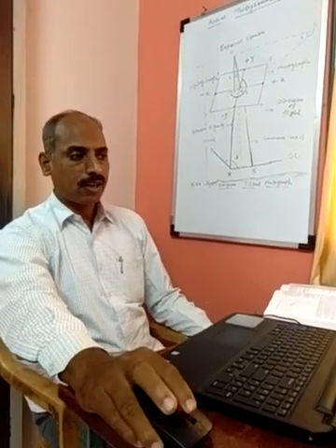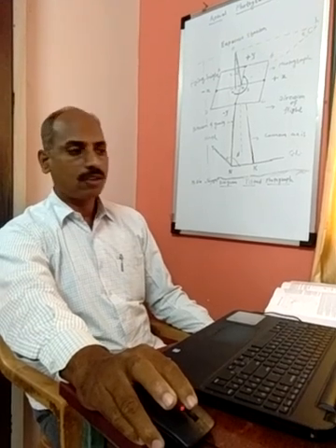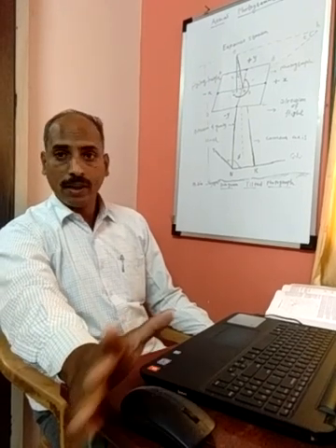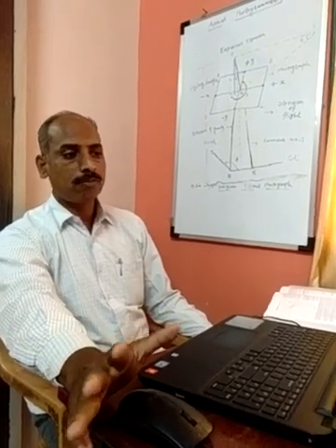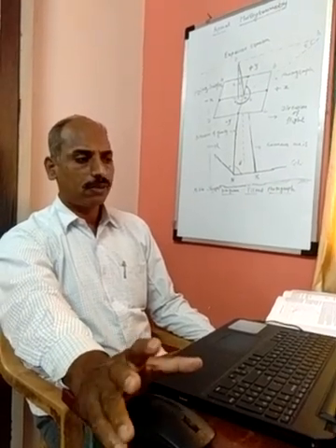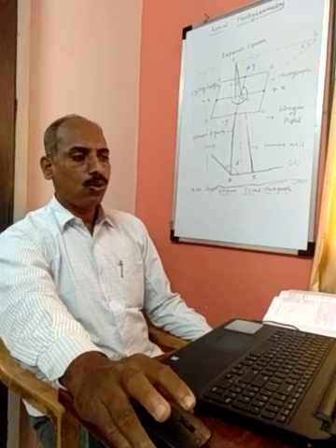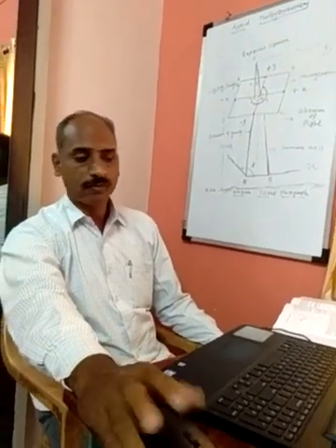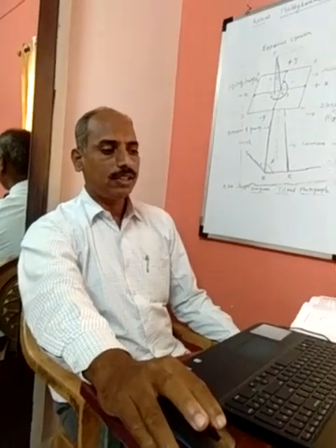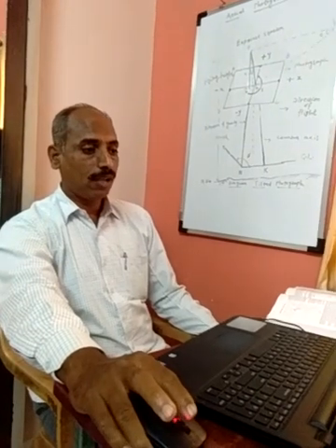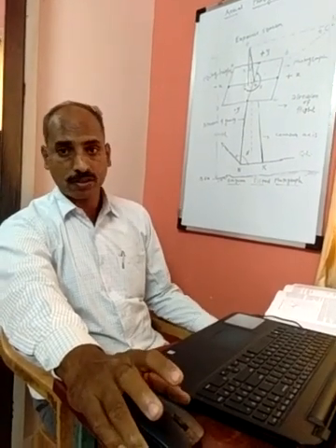The first difference is that an aerial photograph is a 2D, two-dimensional view of an area at an instant of time, whereas in a map, data is collected at some point in time. Then the second difference is that there is no uniform scale over the whole area in an aerial photograph, whereas a map has a uniform scale. Then the third is that an aerial photograph has perspective projection, whereas a map has orthogonal projection.